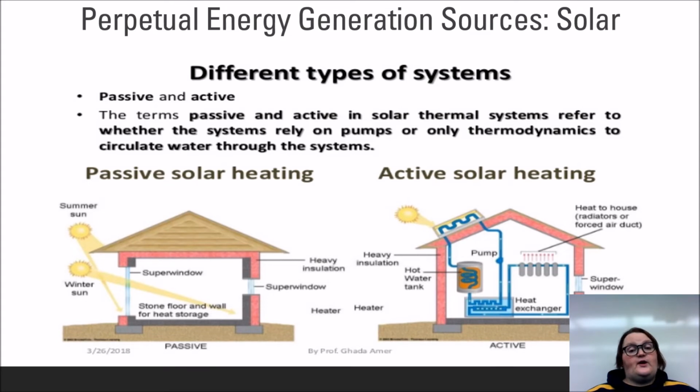The other major way in which solar energy is used is in heating, either passively or actively. Passive solar heating makes use of specific design choices to maximize the sun's energy usage when it is beneficial and to minimize it when it is not. This can come from the use of overhangs that are specifically sloped to block summer sun, but to allow the winter sun, which sits lower in the sky during its brightest, to enter.